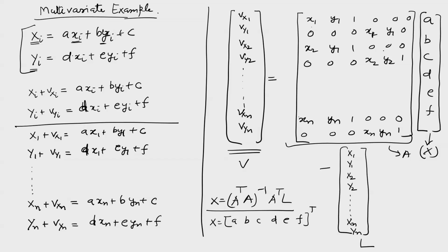At this stage, we need to understand that the observation equation method can be used when the function, or the output variable, or the dependent variable, is given explicitly in terms of the independent variable or input variable, right? And we will also talk about the quality of the parameters. That is sigma xx, which is nothing but (A transpose A) inverse.